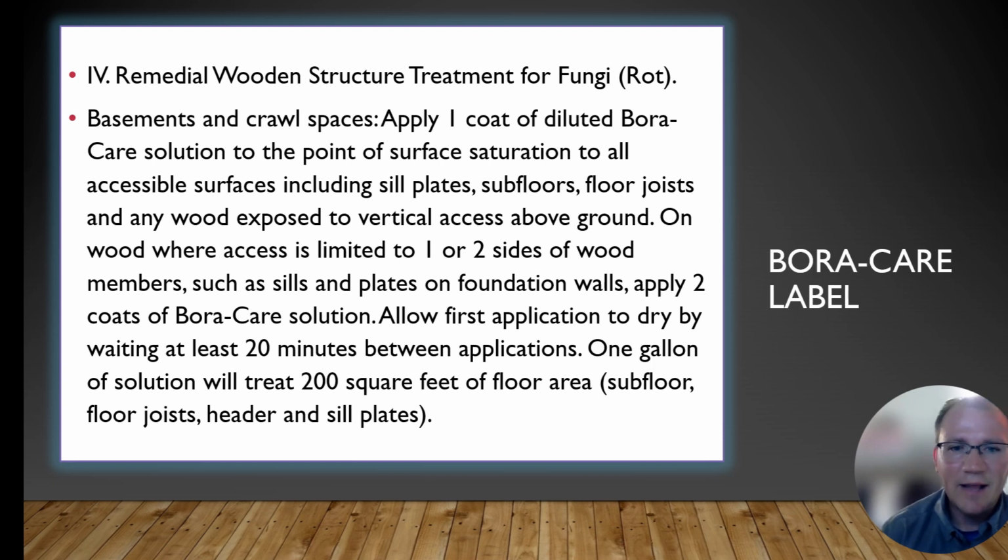So keep in mind, a lot of times you can only get to 1 or 2 sides of wood. I mean, especially on a subfloor or something like that. The floor joists themselves, you may be able to get to 3 sides, so that may be a little easier. Sill plates, again, you're only going to be able to get to 1 side. Most people don't want to have to go through a second application on those, but I let everybody know for the product to work effectively, you're going to have to follow the label, and it does require a second application. So it's a little bit more work, but at the end of the day, we need to get the intended result, and we need to follow what the label says.